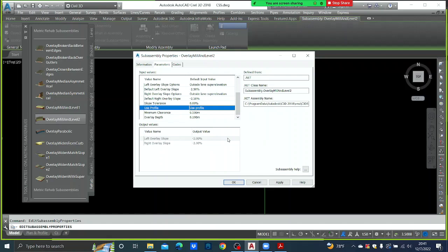Because then we ask, okay, keeping that minimum 200, you create your own profile. If you give here use minimum clearance, it will create its own profile. We don't want that, because we have already created that, and that is not pretty correct, right? Because it is giving just a line that is everywhere greater than 200, so it does not consider the curve length, the K value or whatever. That is just a rough guideline. That is why we use profile.